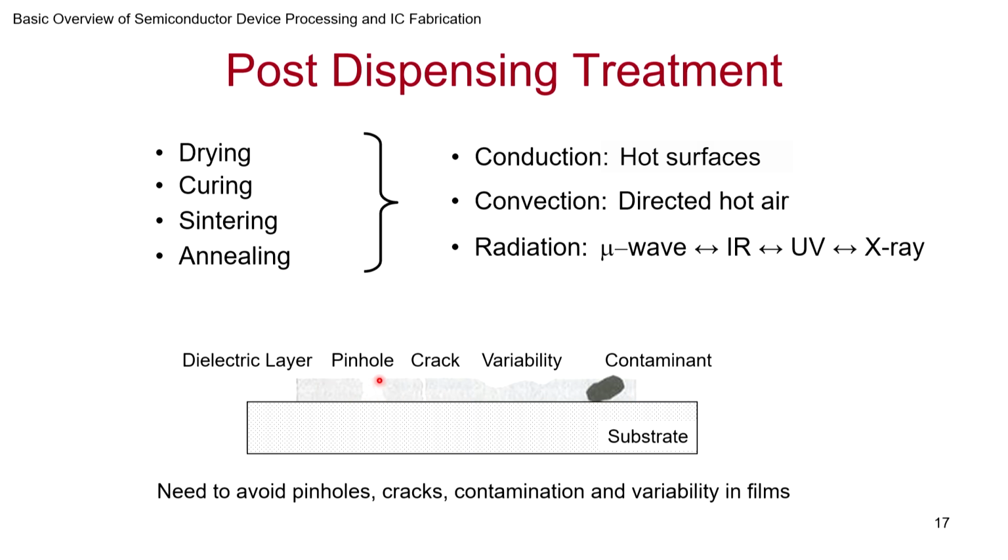You have to make sure they are avoided, and this is the typical process challenge, similar to what we studied in various thin film processes and other things. You want to get a dielectric layer, so metallic contamination should not be there. If it is a dielectric layer that we are trying to make, there should not be any pinholes, because if I put a metal on the top and the bottom there is conduction, the pinholes may end up having a metal going through and it will conduct.